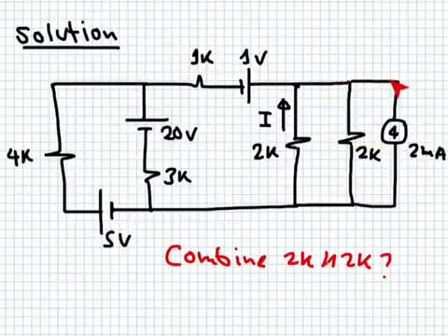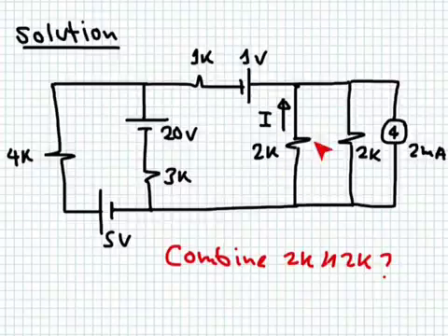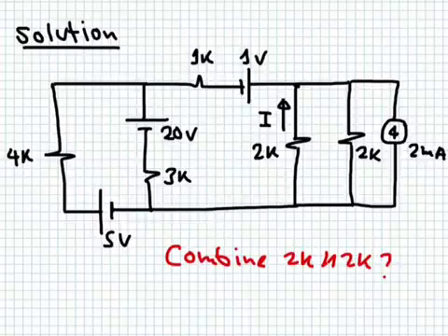So this will give me a voltage source in series with 2 kilo ohm. The value of the voltage source equals 2 milliampere multiplied by 2 kilo ohm. I'm not going to touch this one, simply because the current I am looking for is going through it. This is one approach of solving it, and I will show another approach where we can simplify the circuit further.